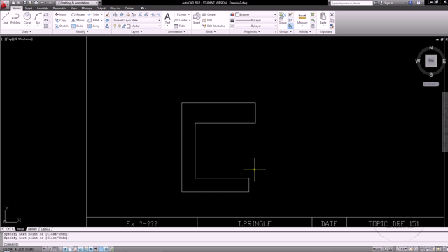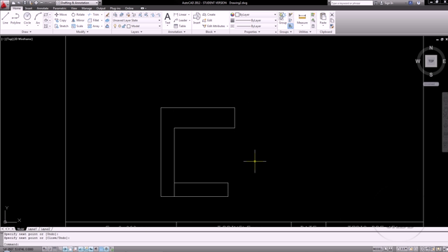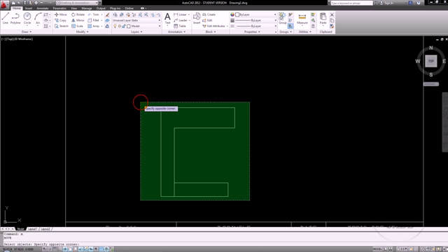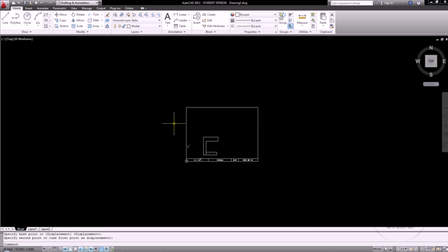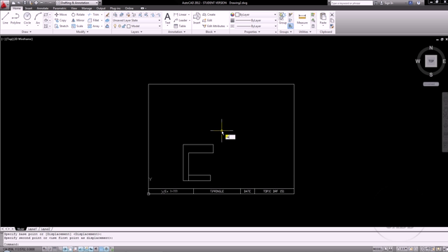close this object off. Now I know that I need a solid line right here to represent where that base is actually a separate piece from the rest of the object. Now this one here might get a little bit tight on the sheet, so I'm going to try to maximize the amount of the sheet that I'm using. I'm going to start my second rectangle from right here, which I'm just going to do a 40 by 100. First thing I'm going to do is set my offset distance, which is 25. Then we'll go 40 by 100,